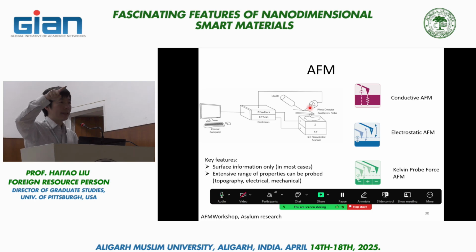It can actually also detect many other things like the phase and so many different things. But sufficient to say that the detector will be able to tell whether the tapping has been in contact with the surface or not. Because once the tapping is in contact with the surface, the magnitude of the vibration is smaller. And what the system can do is it can create an internal closed loop system to automatically lower the surface or raise the surface so that it will maintain a certain constant contact between the needle tapping and the substrate.